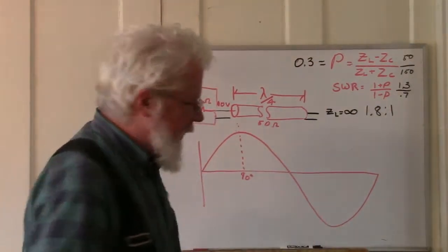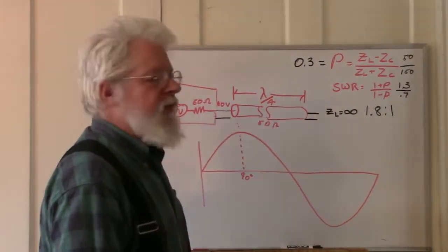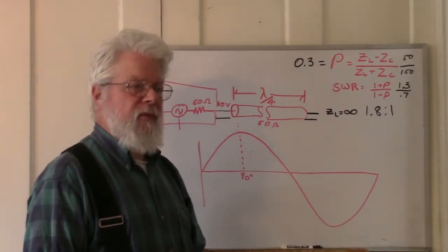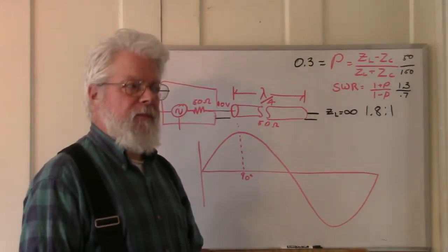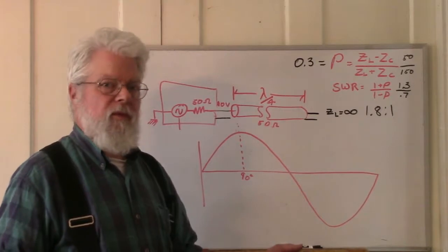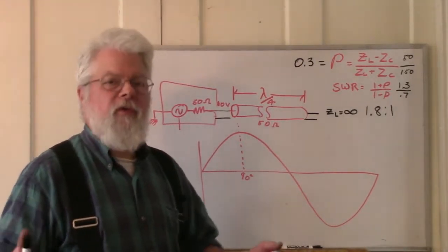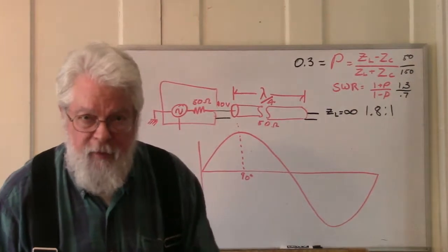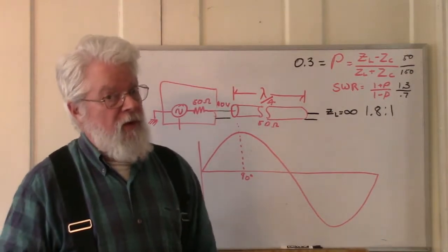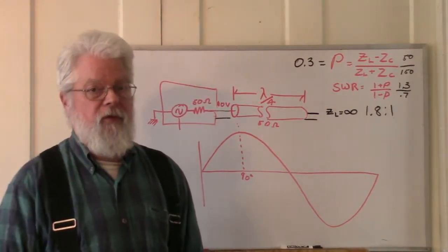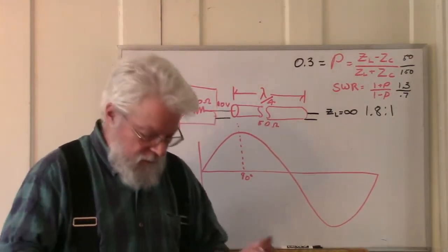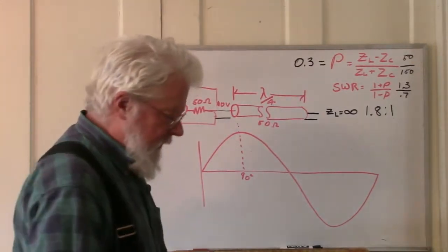Nothing there. Okay? When I get to the end of my line with my 10 volts and my 200 milliamps, what's going to happen? 200 milliamps has nowhere to go. It goes to zero. 200 milliamps cannot flow. However, the voltage has no load now. The voltage is going to jump. Voltage is going to rise considerably. So that's what's going to be reflected back. That voltage.